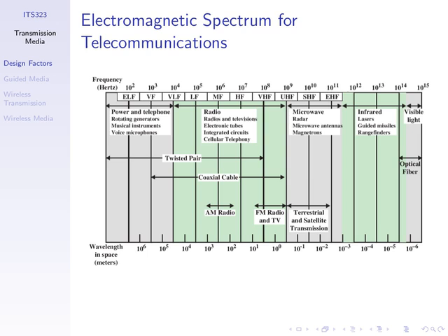So in fact, the signal, as we know, contains a range of frequency components. And the minimum here and the maximum here, and that's our bandwidth of that signal. Now, I don't recall what the bandwidth of FM radio channels is. Let's say it ranges from 87.1 up to 89.1 to make the calculations easy. That is, it has a bandwidth of 2 megahertz.